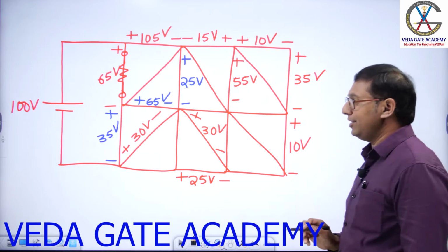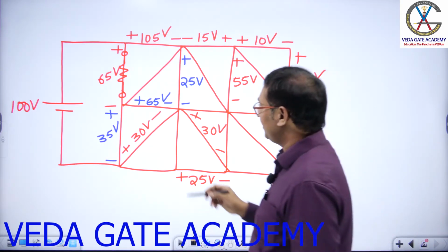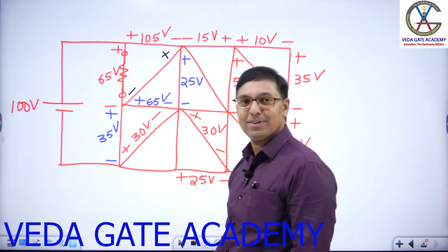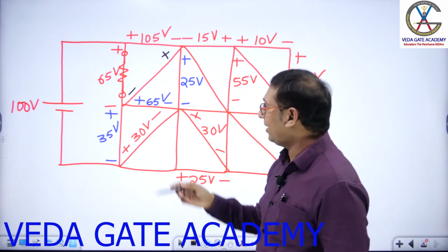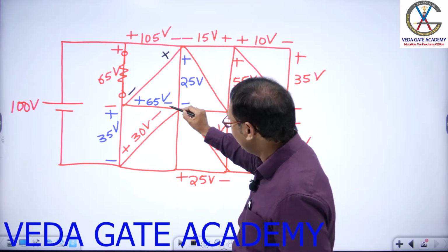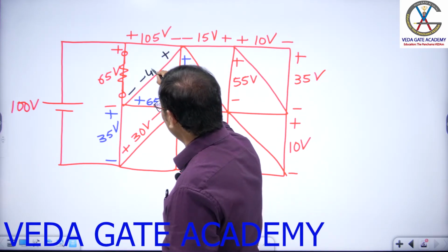Now a doubt comes for the student. Sir, how can you get positive voltages all the time? Okay. For your sake, let me take positive here and negative here. Start at positive, go to negative following KVL sign convention. Come like this. Plus 25, entering it, minus 65. What is the value, sir? It is minus 40 volts.